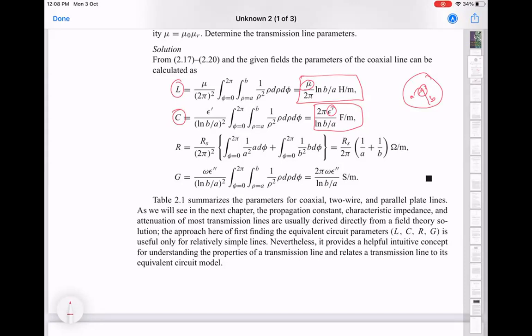Now that is consistent with our initial intuition, saying that a thinner wire will have more inductance. In some sense, it's an extension of the DC idea, even though it's probably not the most correct way of thinking about it, that if you have a thicker wire, it has less impedance to current flow because it has lower resistance. So similarly for inductance also, if you have a thicker wire, it's going to have lower inductance.